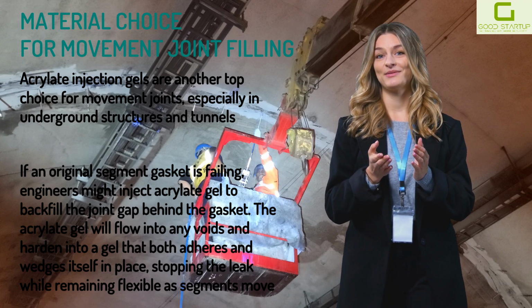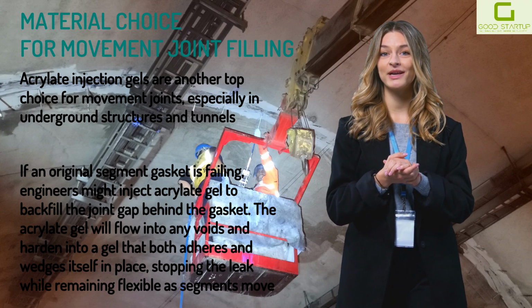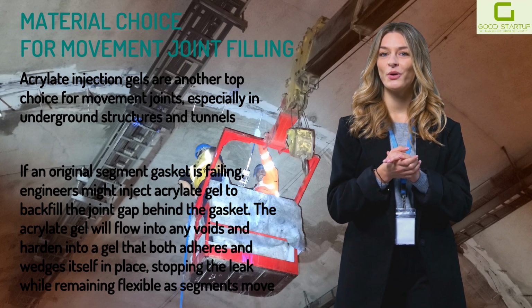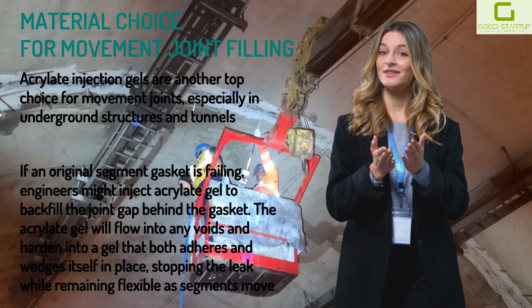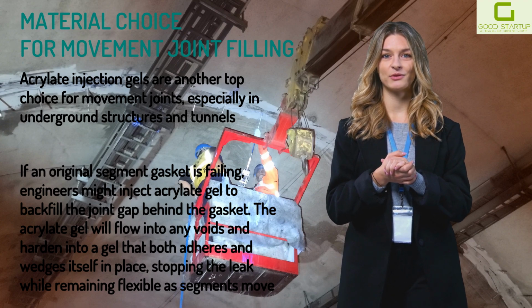For example, if an original segment gasket or water stop are failing, engineers might inject acrylate gel to backfill the joint gap behind the gasket or water stop. The acrylate gel will flow into any voids and harden into a gel that both adheres and wedges itself in place, stopping the leak while remaining flexible as segments move.